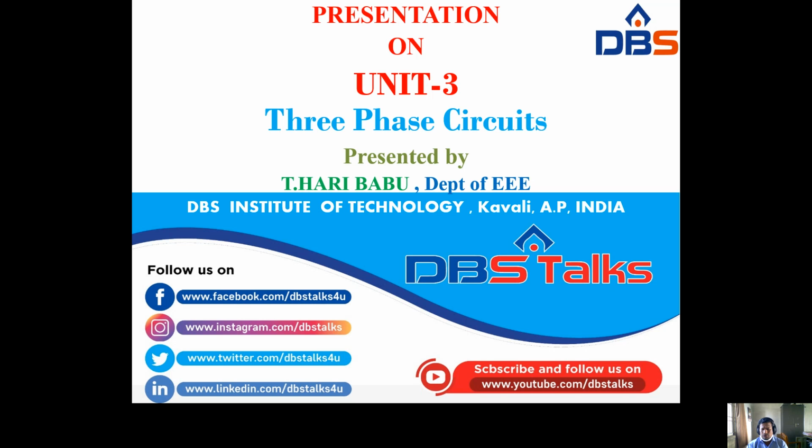By using those two tests, we can determine the copper losses, iron losses, and also the equivalent circuit, that is the shunt branch parameters and series branch parameters, such that we can draw the equivalent circuit of a single phase transformer, and also determine efficiency at any desired load, and also regulation for a given power factor. It may be a lagging or leading or unity power factor, right?